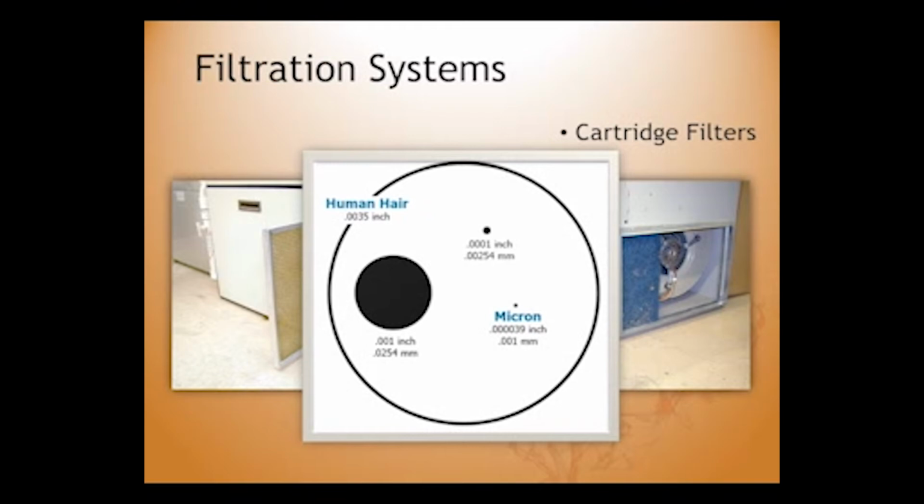We also have electrostatic filters, which use air movement to build a static charge and can remove microscopic particles, and there's no power required for these. Higher filtration also means higher air restriction, so we need to be aware that the finer our filter is, the more stress we're going to be putting on our system as well. We also must make sure that our filters are changed regularly to prevent any damage to the furnace and to help it work at optimal efficiency. Any excessive dust on the filter may spill through and damage the parts within the furnace.